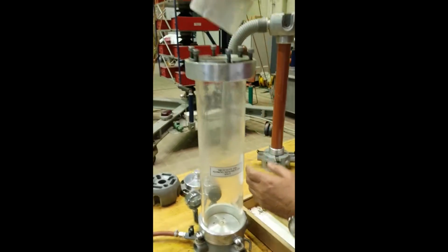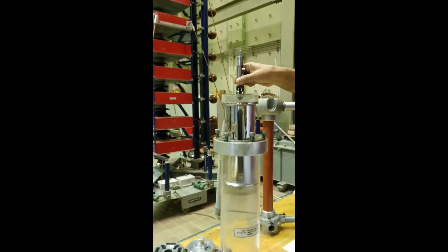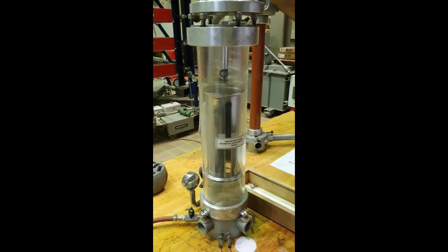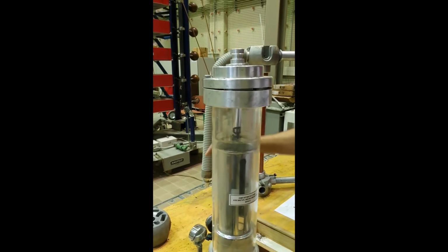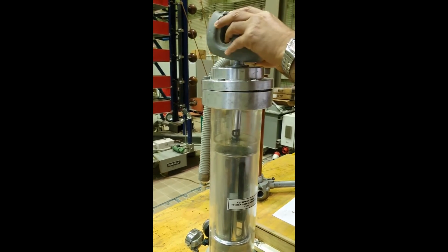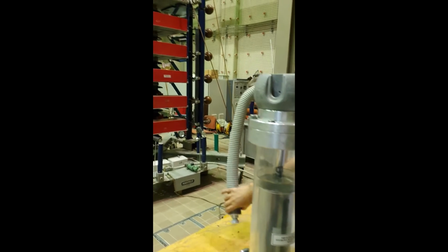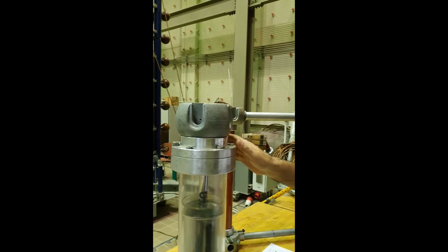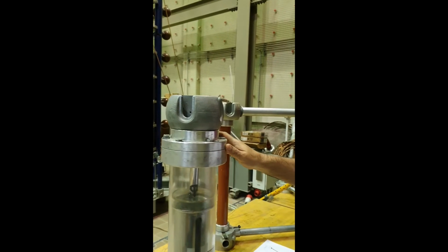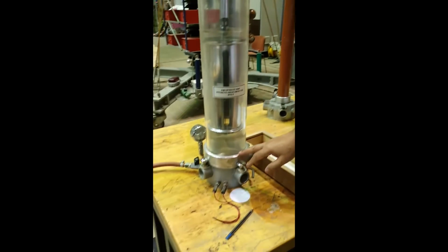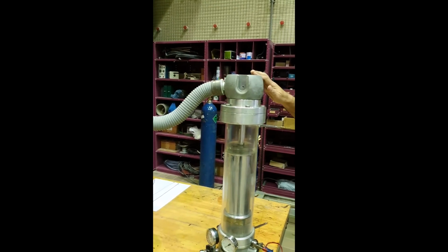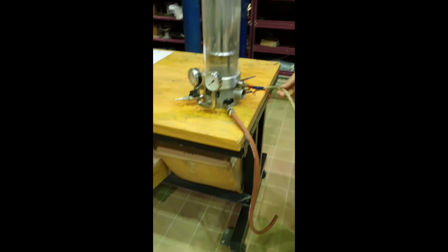This is the chamber; you put it here, then close this and put it here. Our DC supply will come from here. The whole top of this chamber, as you did for SF6 also, will be at high voltage and the lower one will be grounded. This is at high voltage and this one will be our ground terminal, which is going to the ground of the substation. So this is the high voltage line.